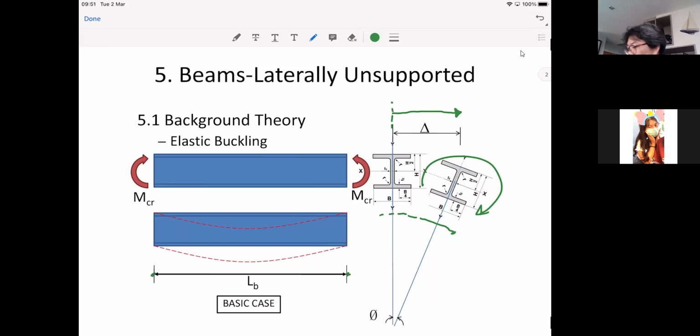That's why we call it lateral and torsional buckling. If you look at the side view of the beam, you see that the beam will deflect down slightly. But the whole idea is that your beam under compression will be forced to move sideways and twist should instability become the issue of that particular beam.